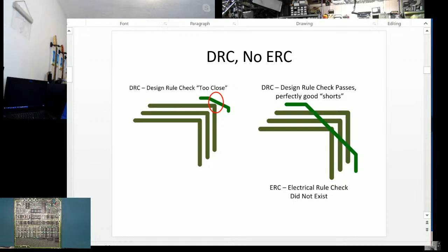And the way the timing worked is if you woke up in NTSC, but it was a PAL crystal, it'd crash. But if it was an NTSC crystal, and you woke up in PAL mode, it'd still work. So we would wake up in PAL mode and then flip to NTSC. So the way they couldn't test NTSC mode was because they couldn't write to the register because the address lines, the selects, these guys, were shorted together.